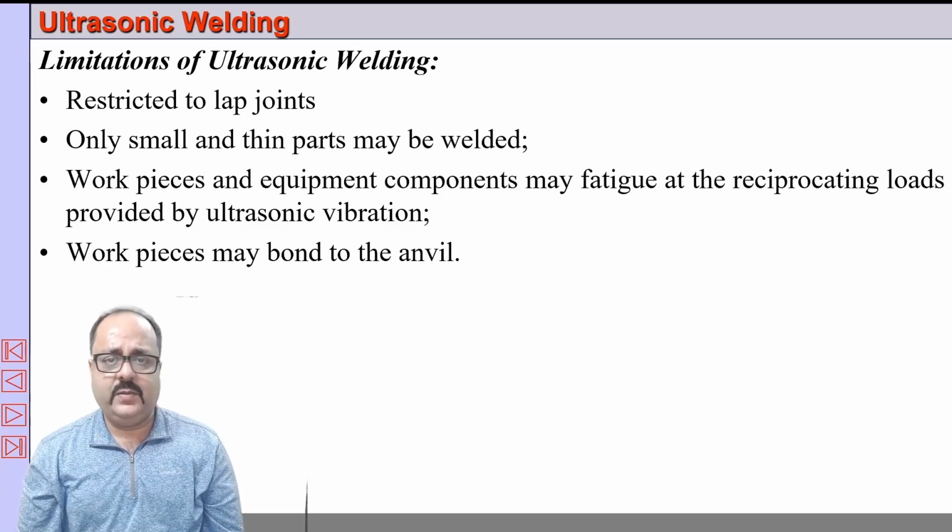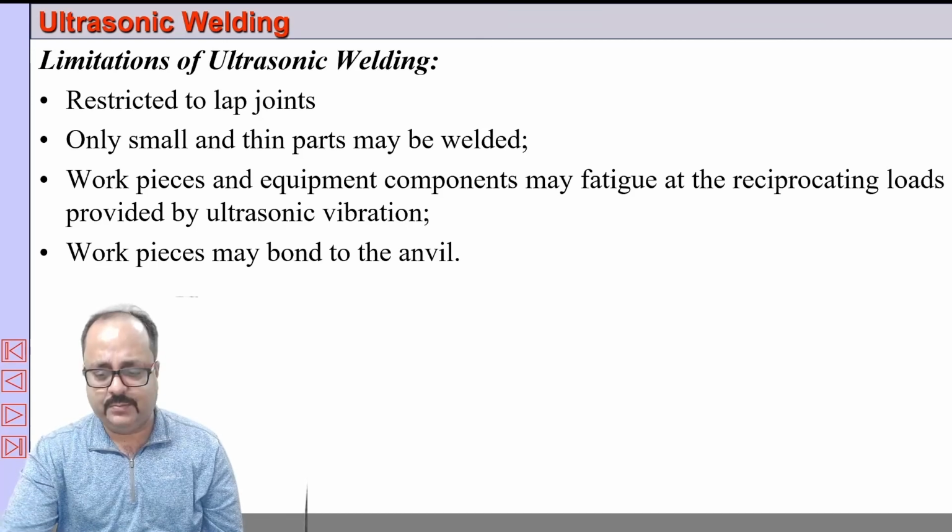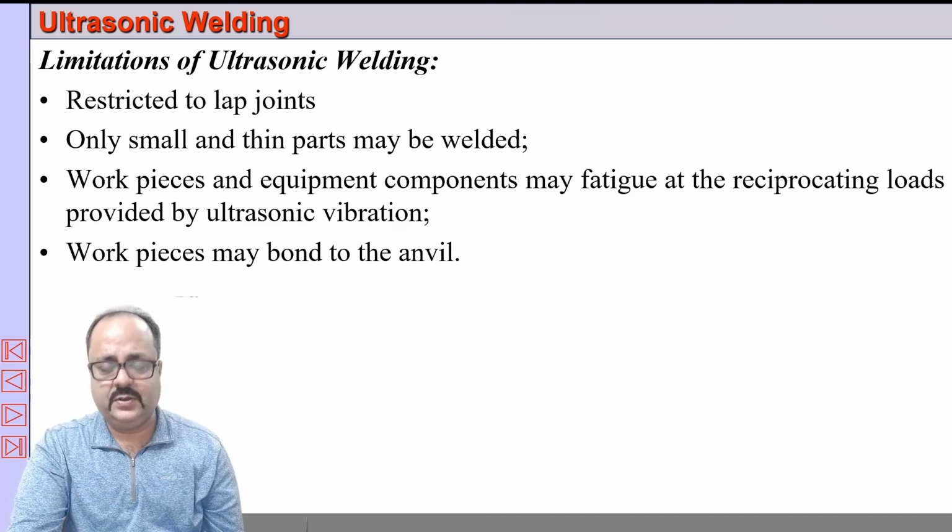The workpiece and equipment may suffer fatigue because of this ultrasonic load. Fatigue can take place, and the workpiece sometimes may get bonded to the anvil as well as to the sonotrode tip. So those are the limitations of ultrasonic welding.